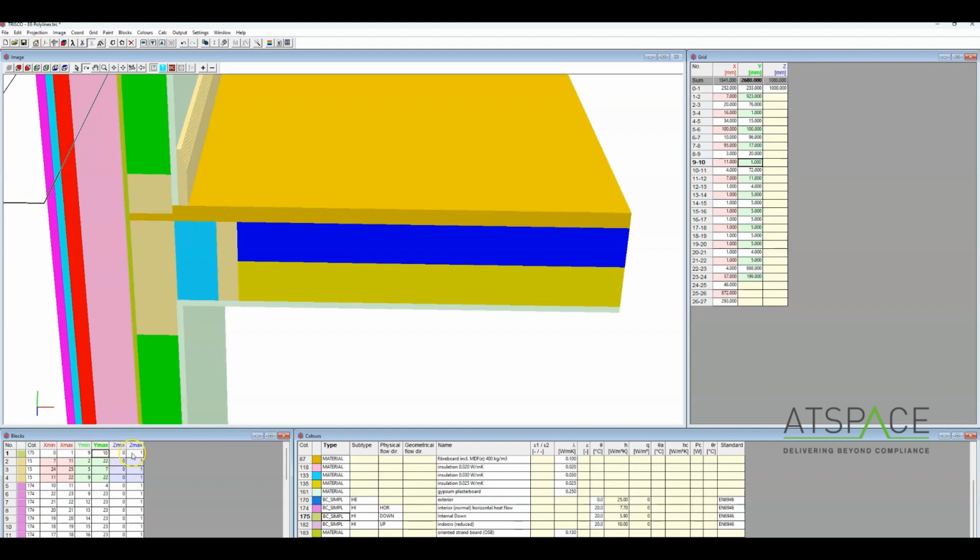Z-axis is always going to be 0 to 1 in this 2D model. And then the x-axis, we basically want to go above this block, but in front of that skirting board. Not that it matters because any overlapping materials are going to supersede that boundary condition, but just to show you how to enter it in if you needed to enter it in more precisely.